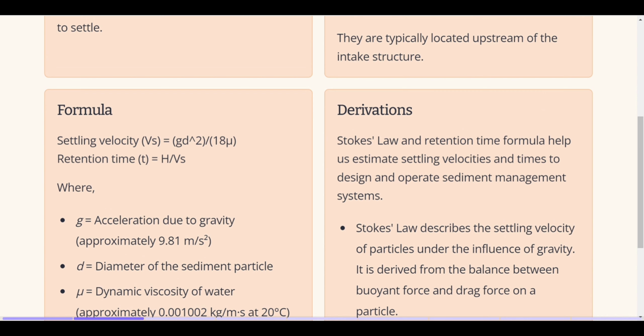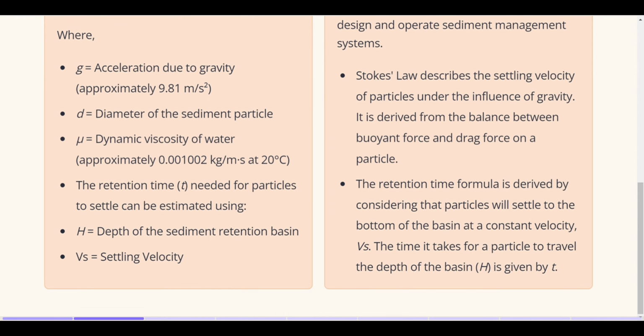Derivations. Stokes' law and retention time formula help us estimate settling velocities and times to design and operate sediment management systems. Stokes' law describes the settling velocity of particles under the influence of gravity. It is derived from the balance between buoyant force and drag force on a particle. The retention time formula is derived by considering that particles will settle to the bottom of the basin at a constant velocity, thus the time it takes for a particle to travel the depth of the basin is given by T.